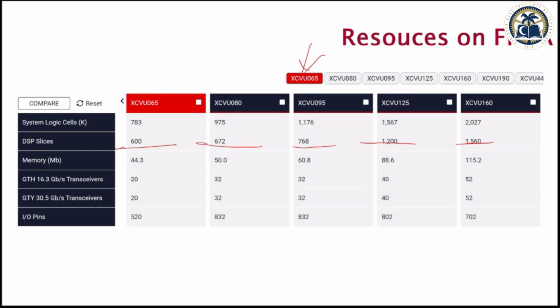Usually when you are implementing something serious, you check how many resources you have and how many you can use. If you run out and you keep adding more functionality, it will be difficult. I have seen people initially not care, designing something that consumes everything, and then nothing is left for the other people working on the same FPGA.